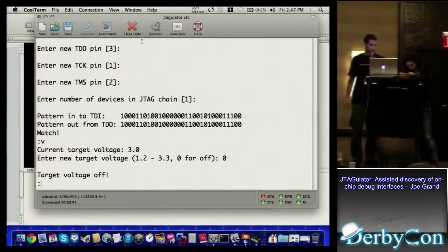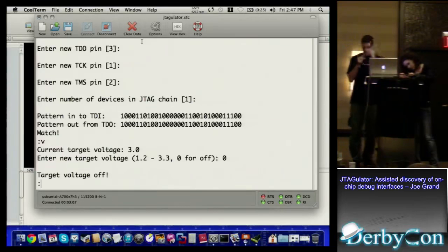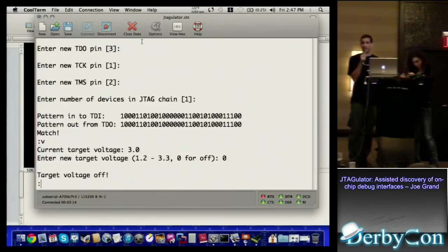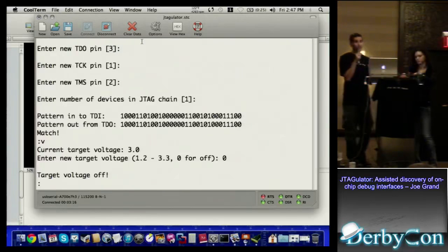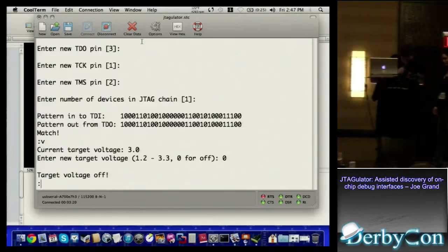Alright, so she's almost done. Now the one thing to be aware of is you need to connect. There always has to be a ground connection, a shared voltage, shared 0-volt reference between the target board and the Jtagulator. So that's like the one piece of reverse engineering you'll need to do is find that shared ground. If you don't connect that, it's not going to work at all. Okay, let's make sure she didn't miss anything. Good. Nice. Okay, everything's connected.